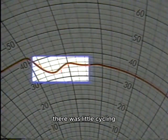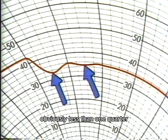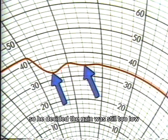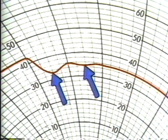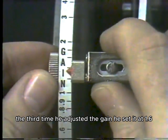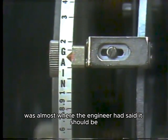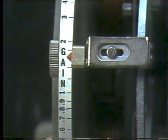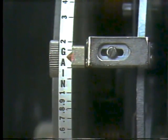There was little cycling, and the decay ratio was still obviously less than 1/4. So he decided the gain was still too low. The third time he adjusted the gain, he set it at 1.6. This meant that it was almost where the engineer had said it should be. He expected it to be either very close or right where it should be.